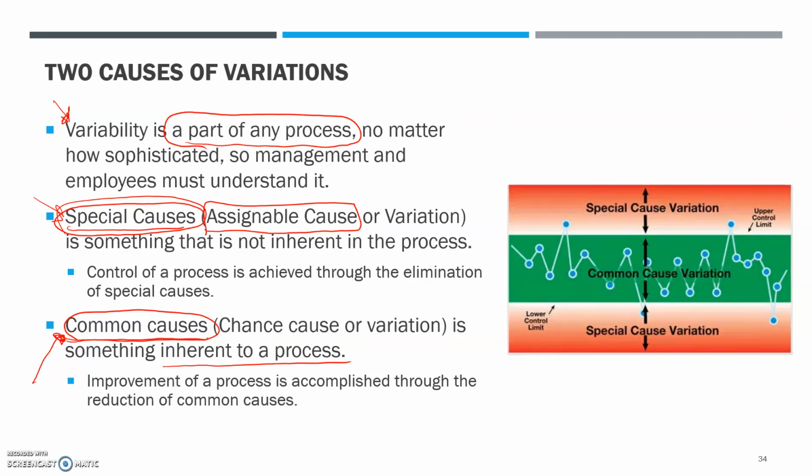So for the line manager, manufacturing manager, or operators, in order to be helpful to them, it is important to identify the special causes rather than the common causes. Understanding common causes will help a manager be more generous toward his workers, but understanding special causes can help a worker or manager identify whether something extraordinary actually happened or not.